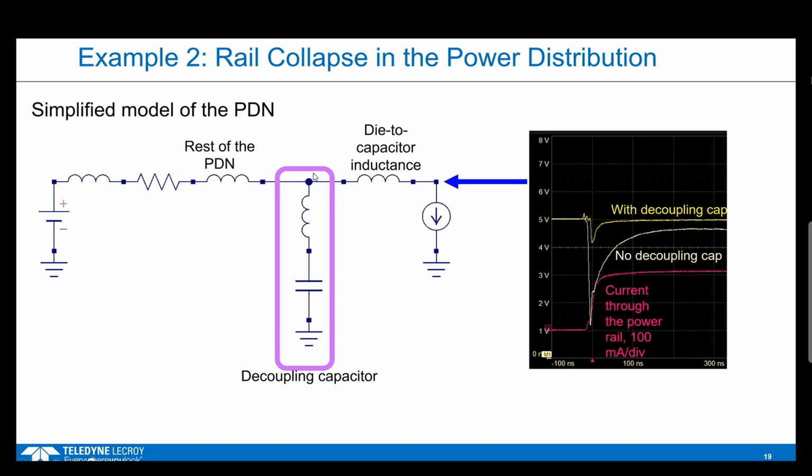And now we add a decoupling capacitor in a location close to the device, and look at that drop in voltage. Yeah, there's some drop. We still want to minimize it, but it's a dramatic reduction compared with not having that capacitor there. The location of the capacitor influences how much residual inductance we have, and some of those features contribute to the best design practices. So this is an example of another type of switching noise. It's switching because it's about the DI/DTs. It's not in the signal paths, it's in the power path.